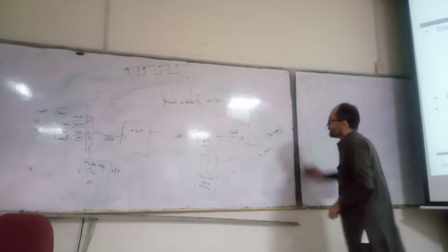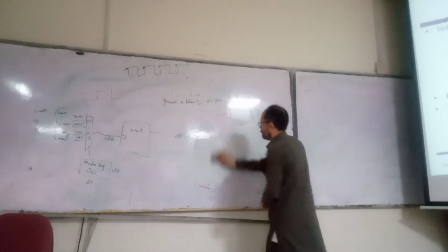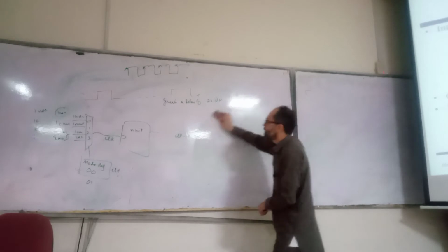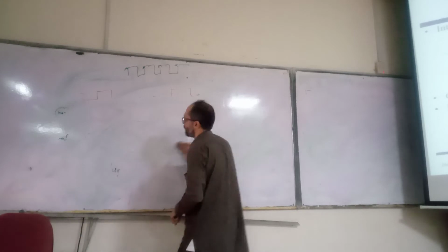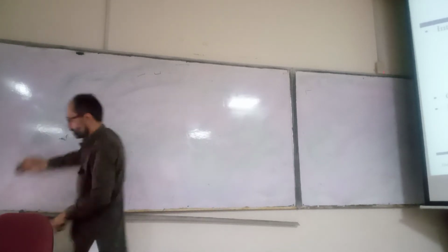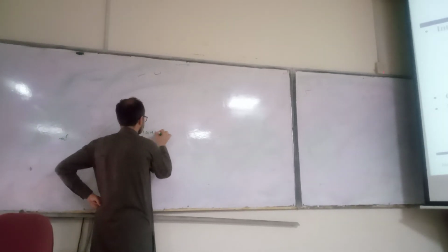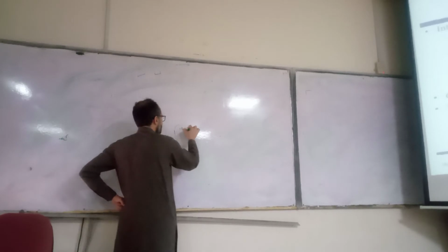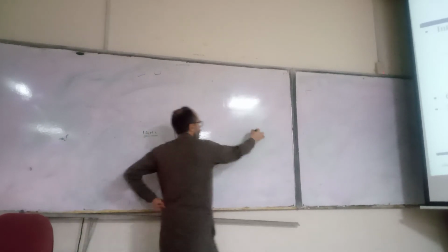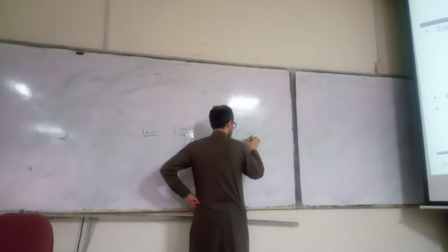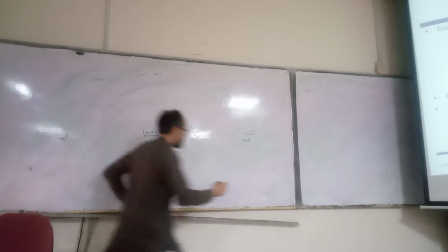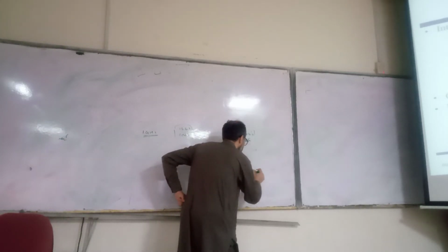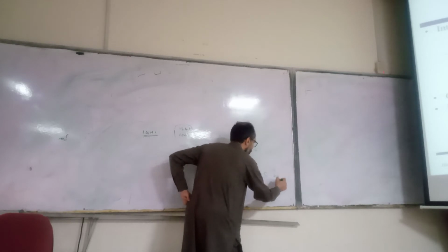Now let's assume that in the market there is only one counter chip available, and your clock frequency is fixed. You cannot change the clock frequency. You have only a single clock frequency, let's say 1 GHz. Now you have a 16-bit counter, and you have another 16-bit counter chip. Your clock is 1 GHz, and you want to model a delay of 9362145 nanoseconds.